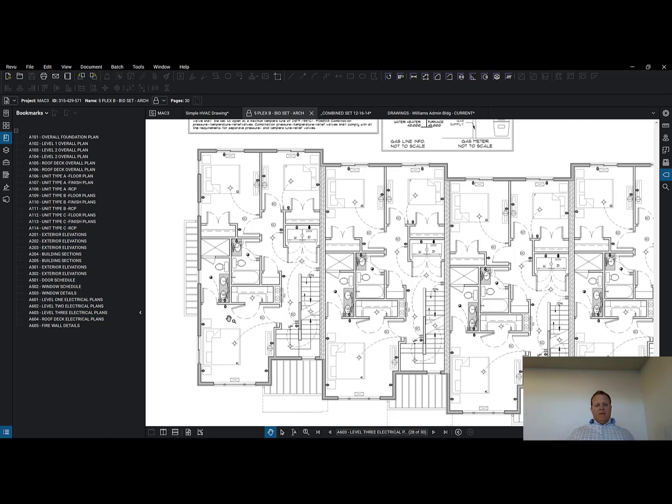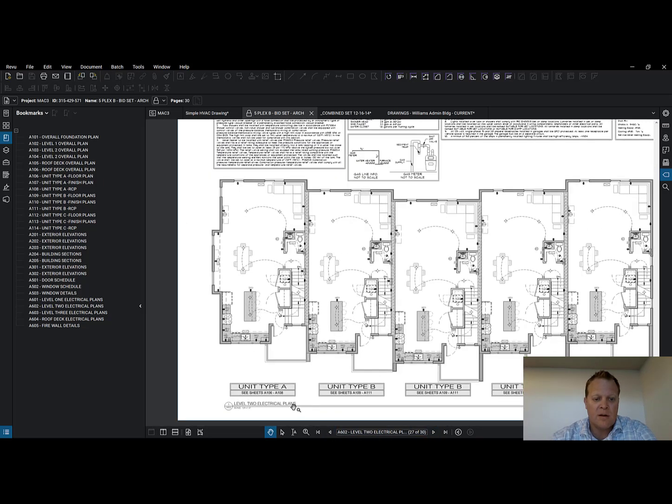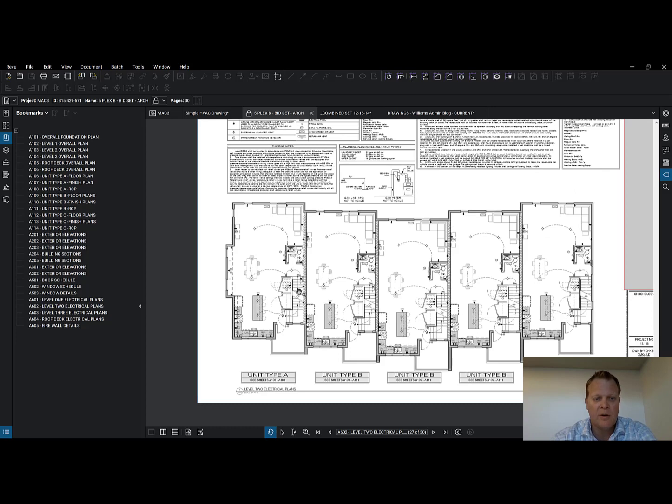So what I'm seeing from the set of drawings as I think through it is that there's a bunch of ceiling drops on this second floor ceiling that have to be done, and we need to make sure that this furnace is planned large enough to get this, and the one on the next floor up above, and the other furnace downstairs is just going to feed that little area. Or we're going to figure out something else we're going to do, but that's all coordination that needs to be done. That's the point. We need to coordinate it.